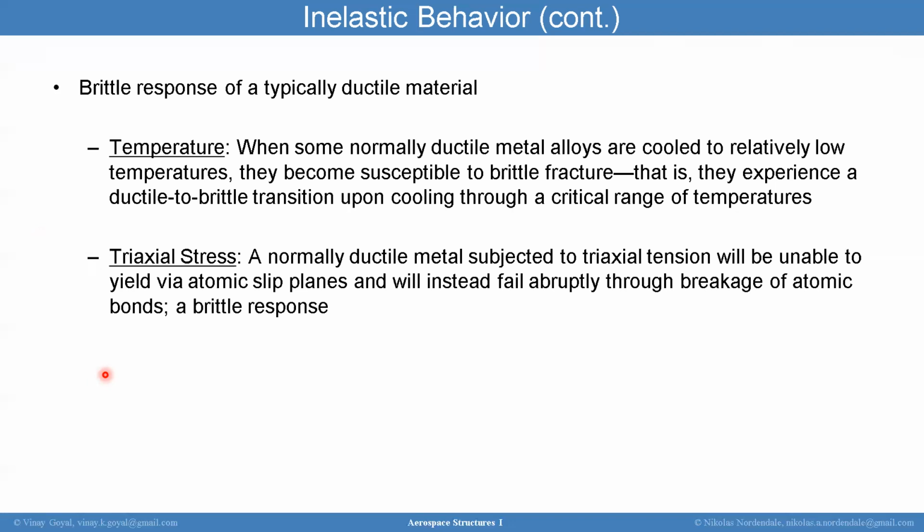By comparison, triaxial compression is the opposite, where you are compressing all the elements towards each other. But again, if it's equally triaxial in all dimensions, you're still not allowing any slippage to occur. And so you won't see ductility in triaxial compression as well. It's just a different failure mode. So these are two environments that can very much change how your typically ductile metal, like aluminum or Inconel or steel, may behave very brittle if it experiences these operating conditions.